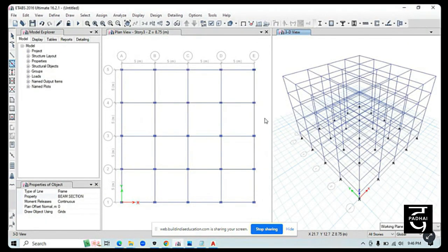So see, this is a very simple process by which you can create your material, assign it for your beam, assign it for your column, and after the beam and column, you'll have to go to the tools and select the column from here and the beam from here, and you can simply assign them in your structure. Okay, from the options of one story, all story, or similar story. So this is just the basics.